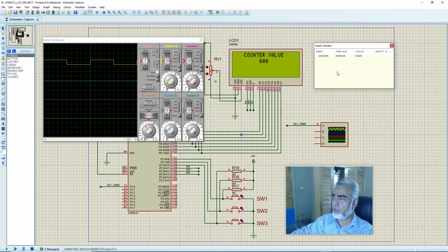done, and here we can find the value of the register is 00. If we press the switch, that is switch 1, we can find the debouncing delay register 1 is decrementing at a very slow speed, and when the value of this register reaches 0, the counter will start counting with a delay of 1 second. And here we can check the counter is incrementing with a delay of 1 second. And now we'll decrease the time for the debouncing delay registers.